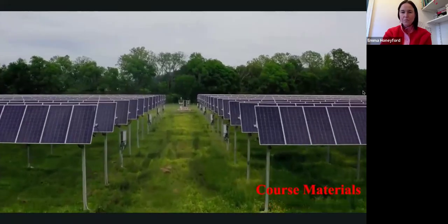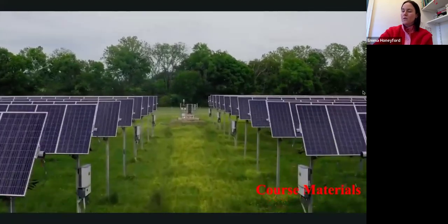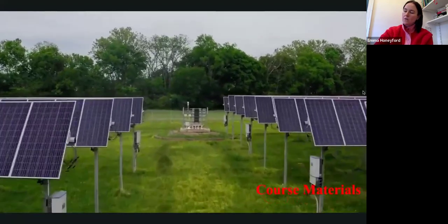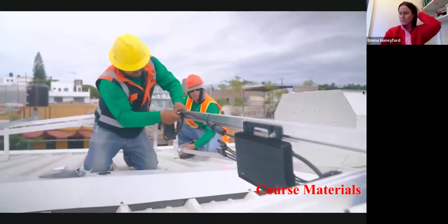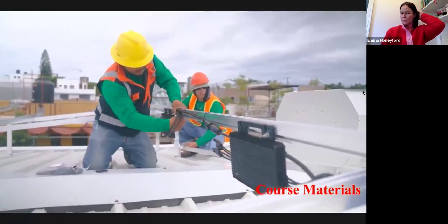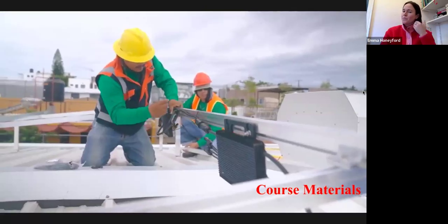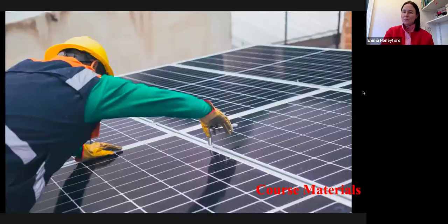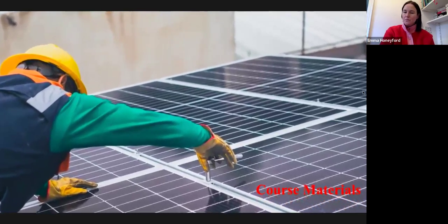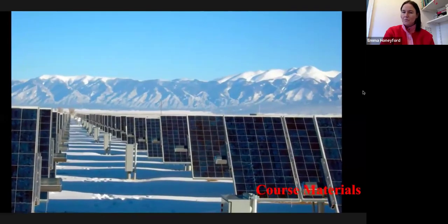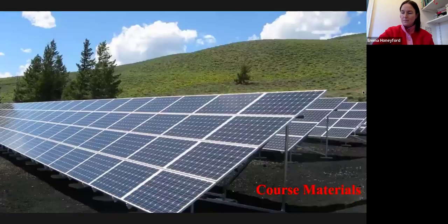Grid modernization. Grid modernization is the process of upgrading and improving the existing grid infrastructure to make it more compatible and flexible with renewable energy sources. Some of the steps involved in grid modernization are enhancing the transmission and distribution lines to reduce losses and increase capacity, investing in flexible generation sources such as natural gas plants or demand response that can ramp up or down quickly to balance the grid, and diversifying the renewable energy portfolio across different locations and technologies to reduce the risk of simultaneous outages.